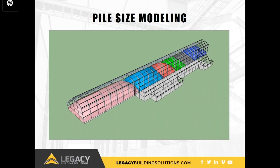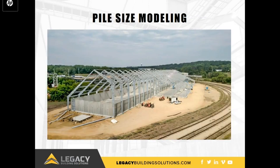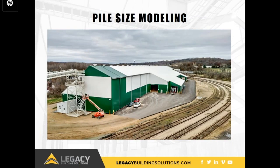The customer needed to store 6 different products in separate bins. The Legacy team created models to show the size of each individual pile. This model demonstrated how the product will fit in the available footprint and determined the height of the concrete barriers used to create storage bins. The building storage cavity was designed around the piles. After the storage area was designed, the team added lean-tos to create space for loading, operations, and equipment storage.